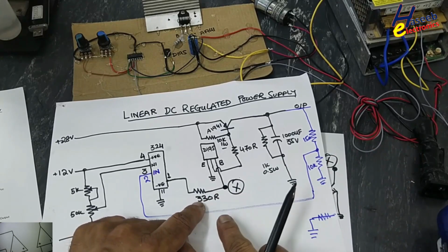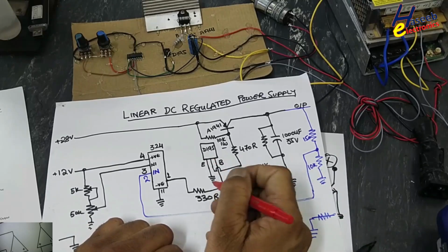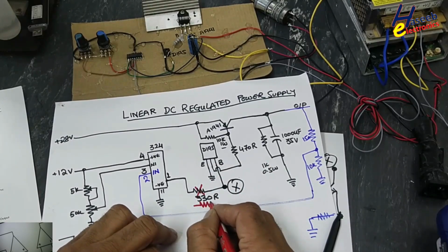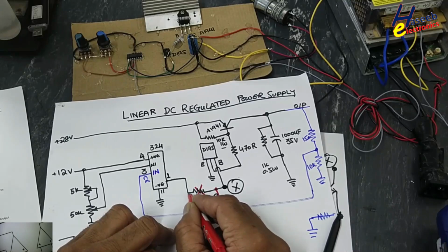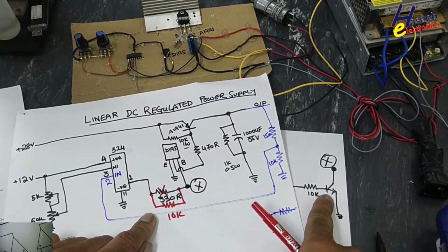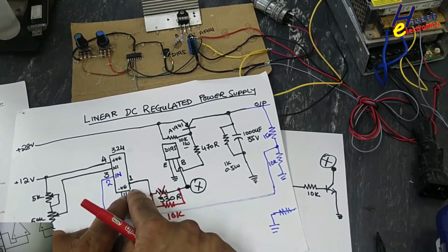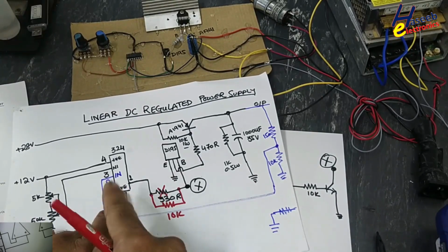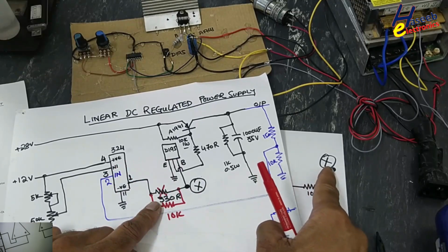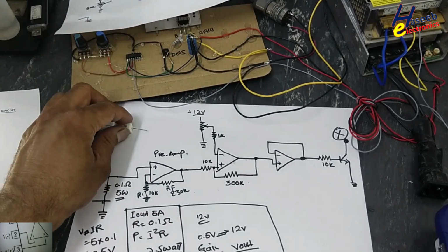In the last session we used a 330 ohm resistor, but now we will remove it. We will use 10K. When this signal turns on, it will pull down this signal. This IC will not be loaded. Before this it was only driving the transistor, but now we are connecting a parallel load here. Let's connect this circuit now and we will check it.